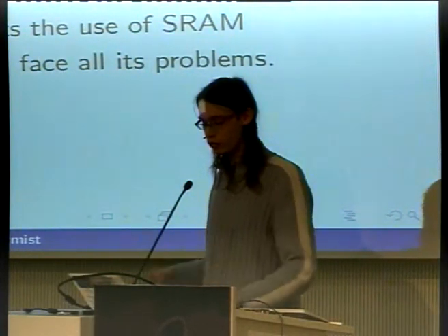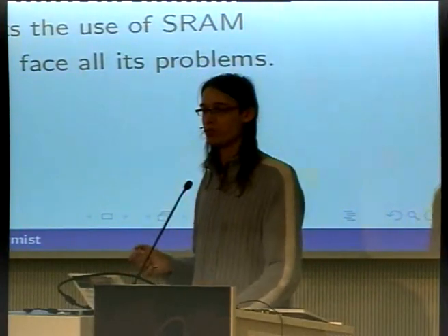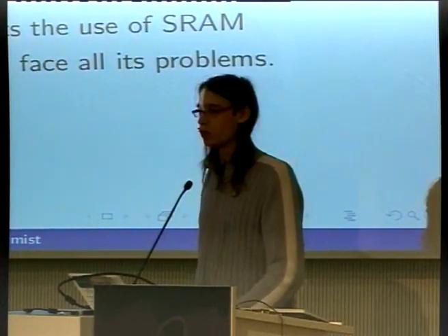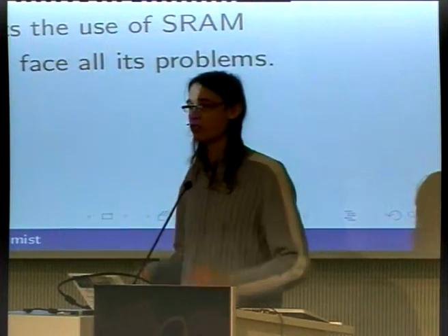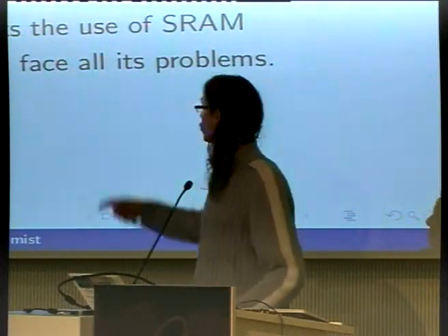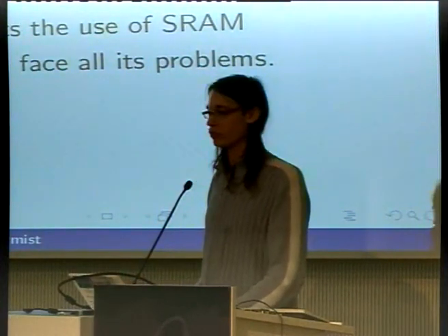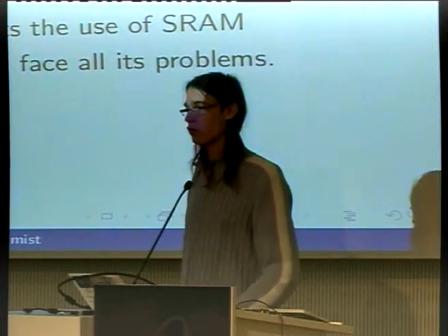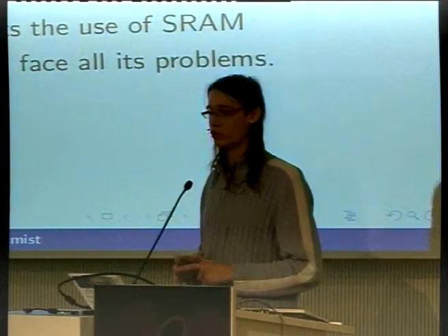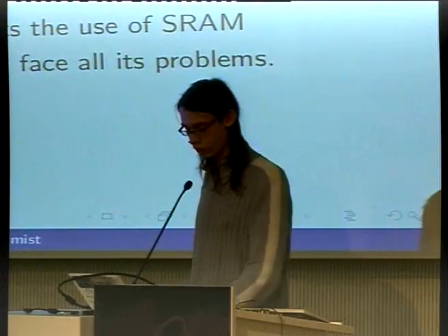The required memory size prohibits the use of SRAM. A very easy memory technology to use is SRAM, which stands for static RAM. But if you need a big memory size, SRAM gets extremely expensive. For example, if you buy a 4 megabyte chip of SRAM, it will cost something like 100 euro, so that's out of the question. So I have to use DRAM, like in computers, for example. You know, SDRAM, DDR SDRAM, DDR2 SDRAM. This is the type of memory that I have to use because of the cost constraint, and this memory is very hard to drive.